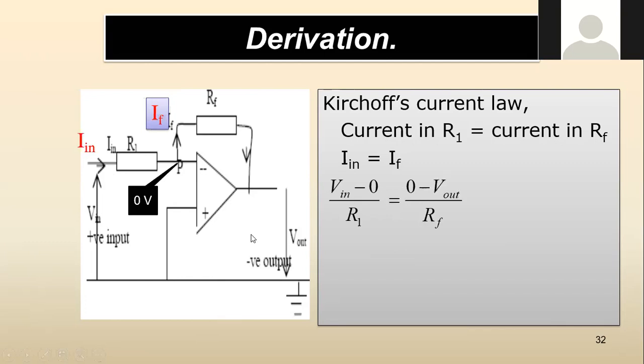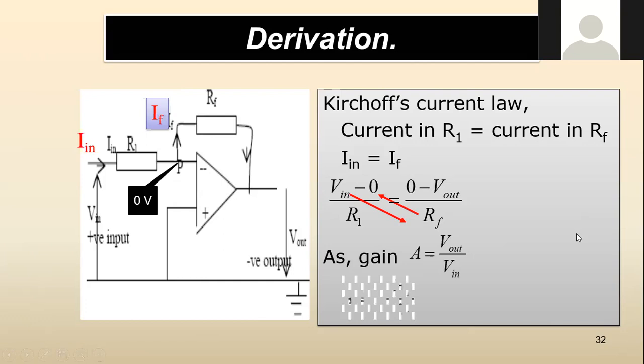Okay, and we go to our definition of gain. The definition of gain is whatever the output voltage is here divided by the input voltage there. From this equation, we take our V in down, cross multiply, take RF up, and then take the negative side to the other side. Take V in down, that's how we get our definition for gain. Take our RF up, and the negative side across, and we get minus RF over R1. Now you are required to know how to derive this.